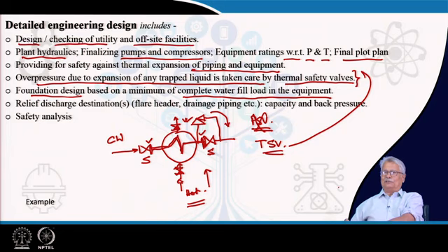Particularly for hydrocarbon columns, you should not consider the hydrocarbon filling up the entire column, because hydrocarbons have density less than water, and during the initial stages immediately after your erection, the entire column is filled up with water and water washed. So, in any case, at least once in its lifetime it will be filled with water, and it must have the mechanical integrity to withstand that. So, note one thing: the foundation design is based on the minimum complete water fill.